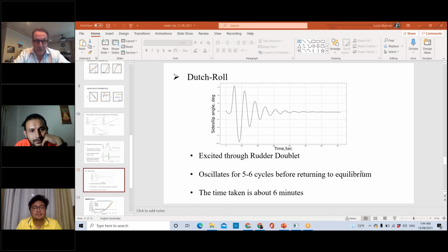My guess is that it will be able to, but sometimes, depending upon where the rudders live, the rudders make their own rolling moment, and then you find it's more challenging to get what you want, and you have to get aileron in the picture too. But I'm pretty optimistic that with rudder damping, even an old school radio control simple rate gyro damper that's not even in the autopilot, just outside, would probably be a nice feature on the airplane.